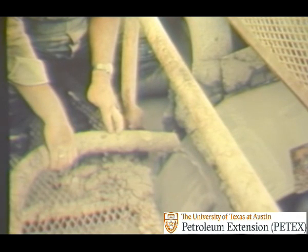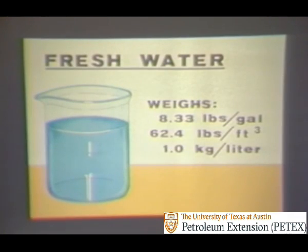As we watch a derrick man adding water to mud, let's talk in detail about the water phase. The kind of water affects the way the active solids react. So water affects the viscosity, gel strength, and filtration properties of the mud. Fresh water, like the water we drink, is often used in a mud. It contains little, if any, salt, and little or no substances like calcium or magnesium. Fresh water weighs about 8.33 pounds per gallon, 62.4 pounds per cubic foot, or 1 kilogram per liter.